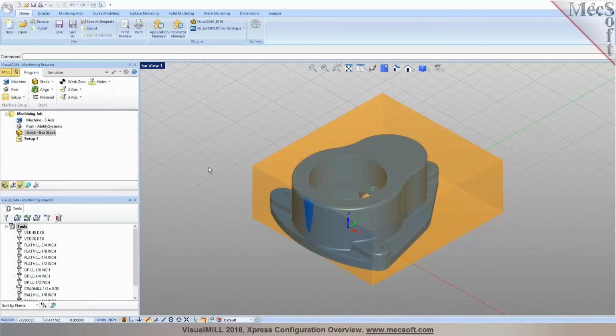So that stock from selection, you could actually export your stock from the current cut material simulation and then import that again as a stock selection. Is that basically what you can do? That could be one of the applications. You could also have your stock modeled in your CAD application, and then you can select it to define a stock by selection as well. Okay.